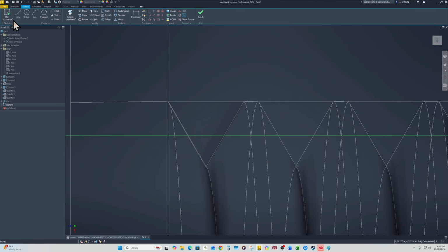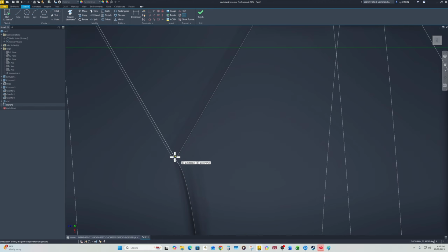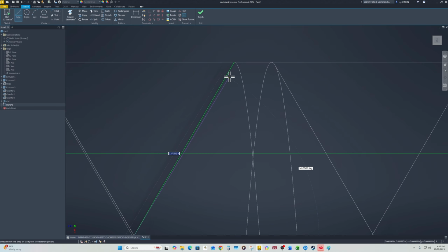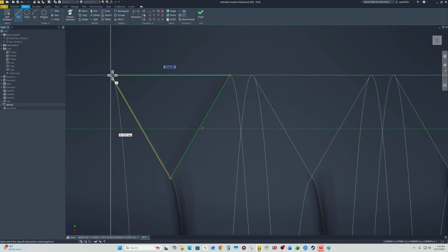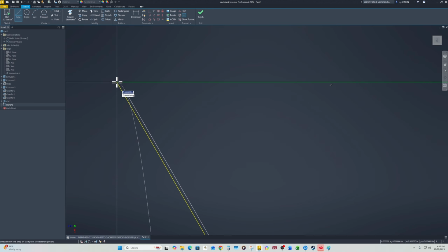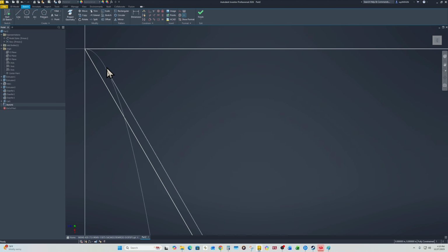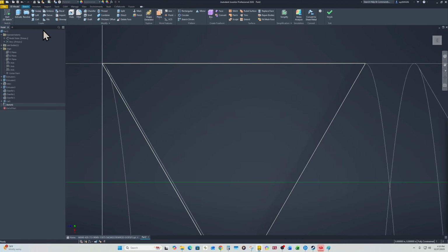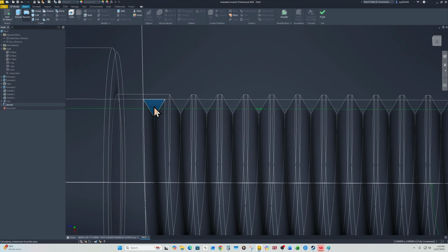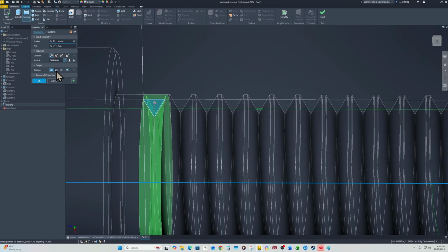And then we're gonna just draw this out. I know from experience from this point, it starts here, you go here, you go here, and then you finish off where you started, right here. And it should all be straight, it should all be good. So I'm gonna do revolve and select axis, cut.